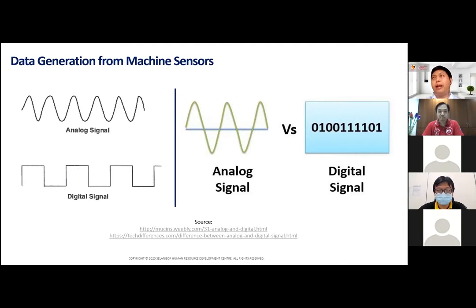So let's say if you look at your production systems, what are your digital and what are your analog signals from a machine? So a very common one would be digital signals come from your tower lights, your traffic light, red, green, and yellow. So it's either red light on or green light on, right? 1 or 0. So some machines, you have temperature sensors, right? So then temperature sensors are your analog signals. So this can already tell you what is happening in a machine from having an analog and digital signal, right?